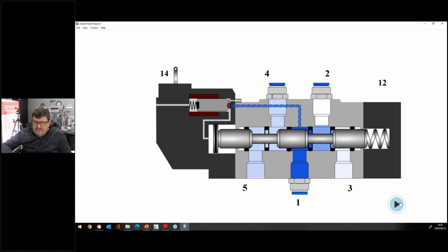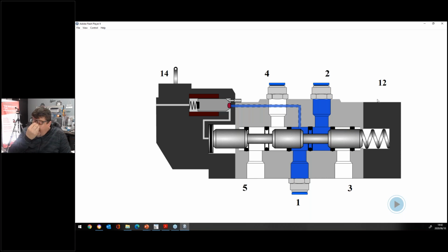on the right hand side, if I release the power, if I de-energize it, the spring will reset my single solenoid valve, and now the airflow is from 1 to 2. That means my spring actuation, or what we refer to as reset, will reset my valve to go to the unenergized position. All right, now the air will flow from 1 to 2.